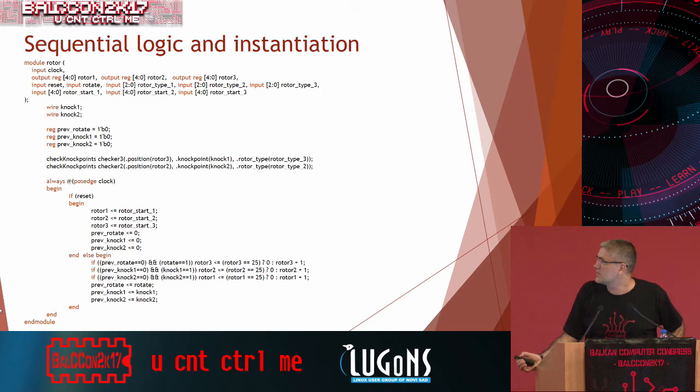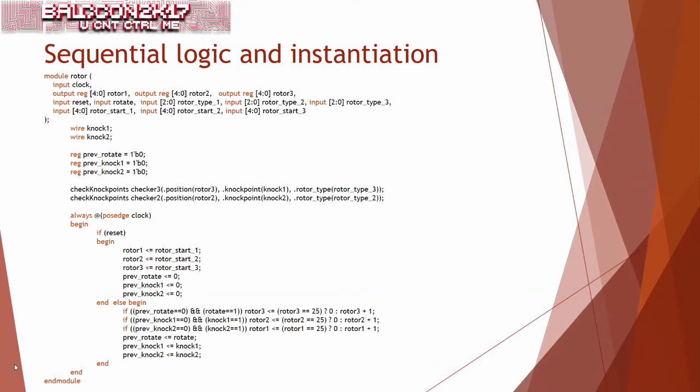And here is just the logic, how we reset, and you can see that here we have less than equal, which means non-blocking assignment, basically. And those lines are assigned at the same time. Order is not important. And in the always blocks, if you put equal, then the order matters. If you put less than equal, then it's a non-blocking assignment, so it doesn't matter. I mean, I just want to initialize this all at once.